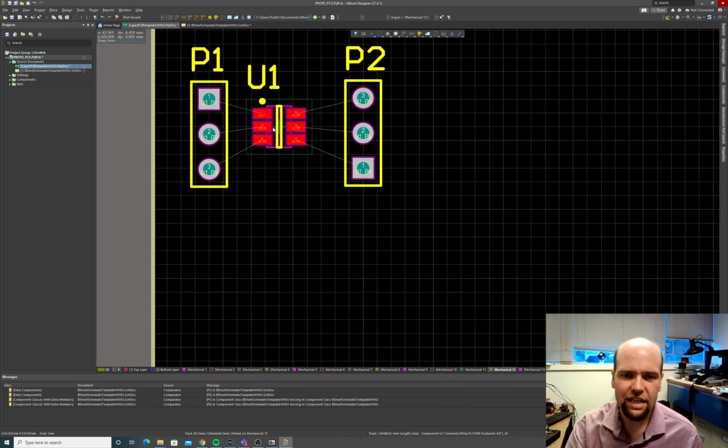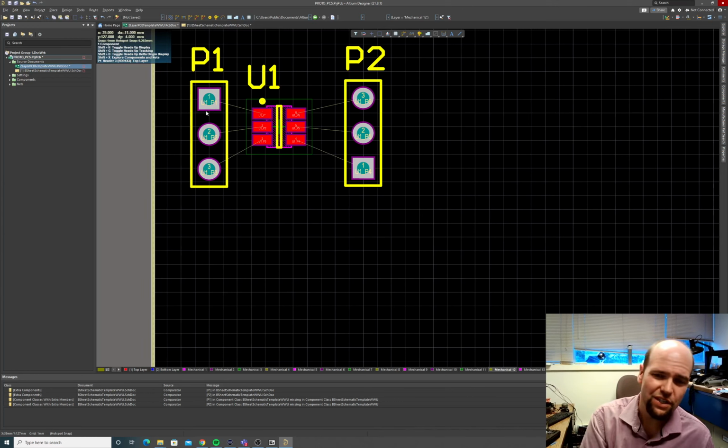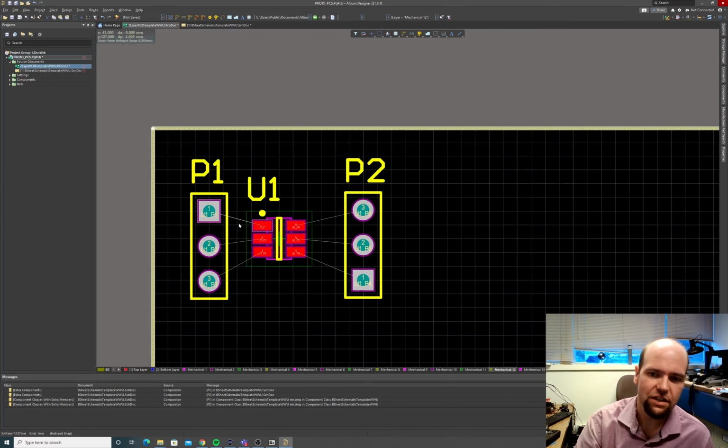Okay, so now the nice thing is these headers right now are all sort of aligned with the pins, right? I had to rotate them and move them around. It's a little weird. These have a square, usually a square designates pin 1, which is useful here. So it would be nice if we used a header that didn't have a square on this side. It doesn't really matter in this particular case though, so it's not going to be a huge deal. I'm going to show you a couple options that we have.